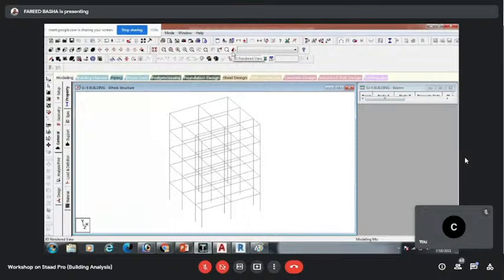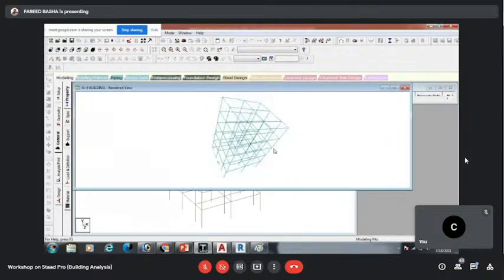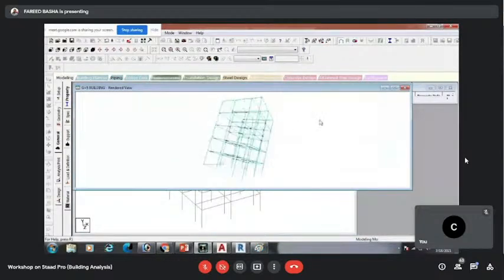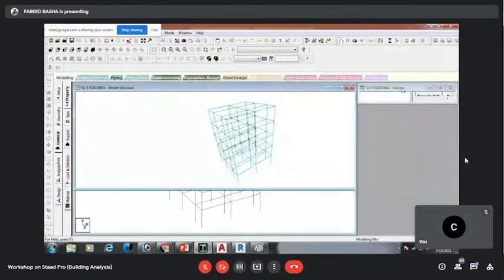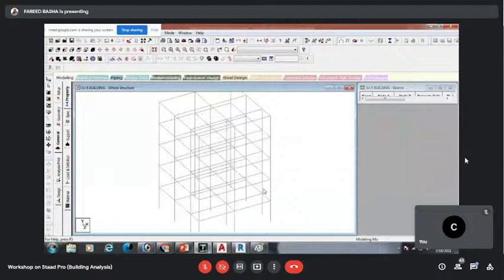So you can see in our 3D render view how this project will look. Are there any properties available? We just created a beam and columns. Now I am going to create the slab. I am going to create the slab here in the first story. To select the first story, we have a 4 node plate option here. So we have to select this 4 node plate option and click node to node.